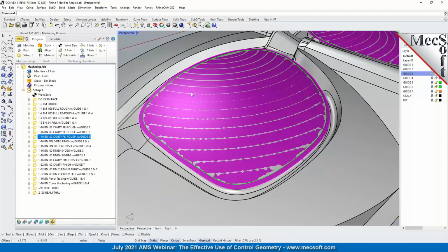You can use this. Well, I'm not going to call it a trick, but it's just a way of using surfaces to guide your toolpath in such a way that you're guiding it as it moves over this parting line. So we have an interior island, we have a parting surface in that island, we have a shutoff parting line right here at this edge.